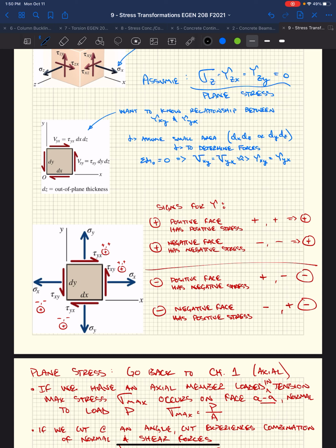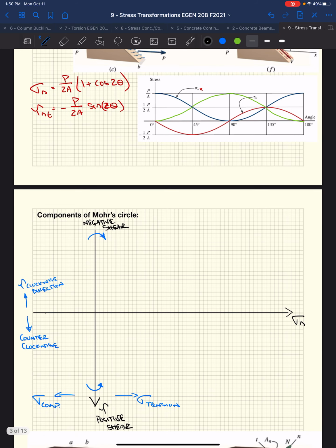So you would go through and you'd have a known stress state. Say this was the known stress state where we have tension on two faces, normal, and then we have shear stresses, right? So you'd go to this and say, okay, I'm going to plot my X normal stress, and that's attached to this shear stress on the X face. This shear stress on the X face is rotating this block counterclockwise, right? So it would be on the bottom side of our Mohr circle, counterclockwise. So we would plot a positive tension, normal stress, associated with a shear stress that was down here.